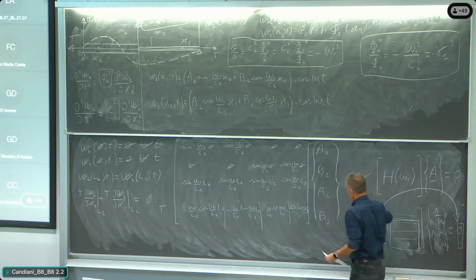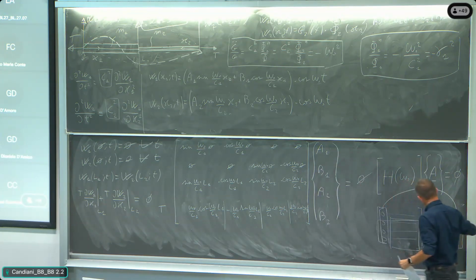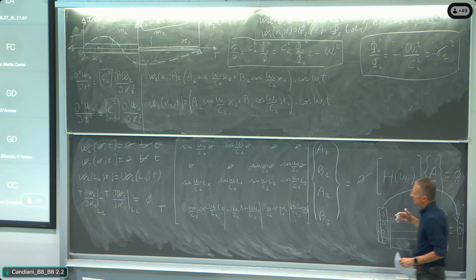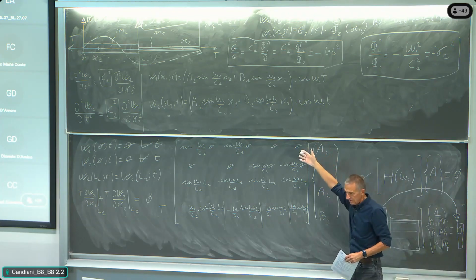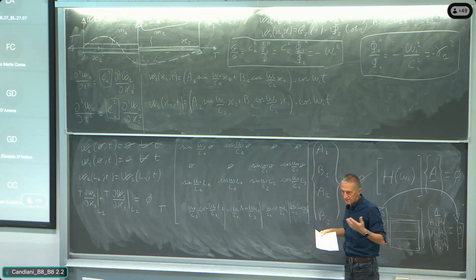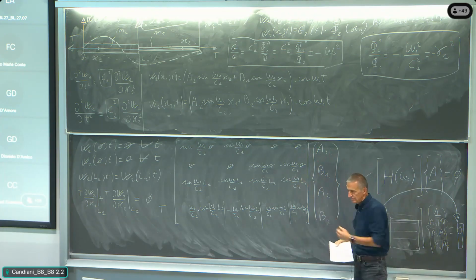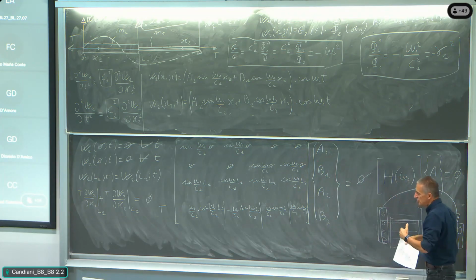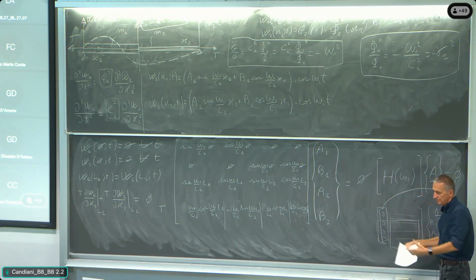So the consequence is that those numbers are determined unless the scale, that the modal shape that we are finding is defined unless the amplitude, all right? So we are giving a shape to the modes of vibration. We are not giving how much they are moving, okay? So we are just saying the shape, which is the shape of the mode of vibration.